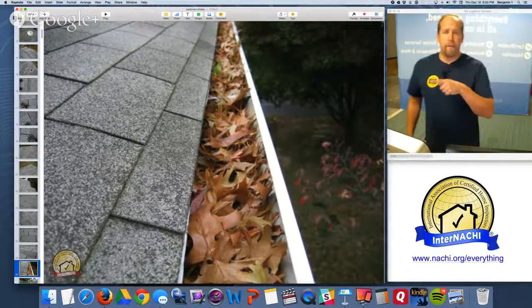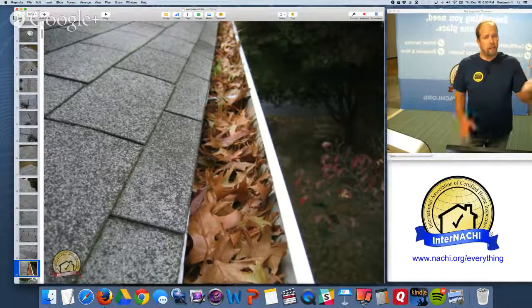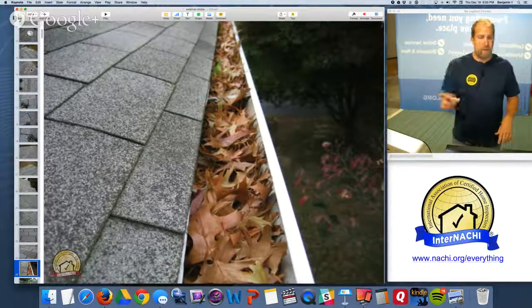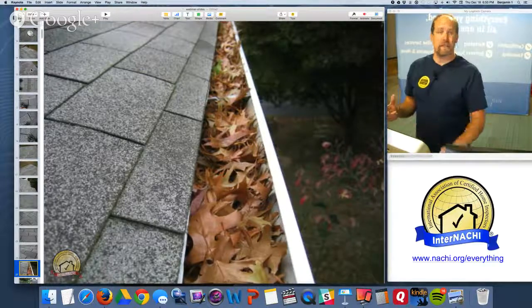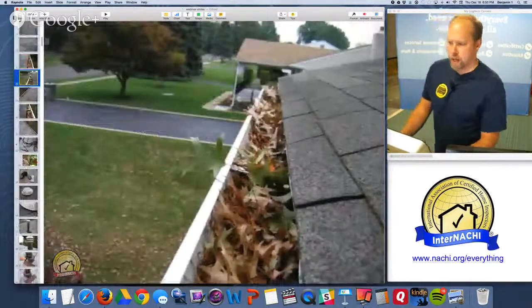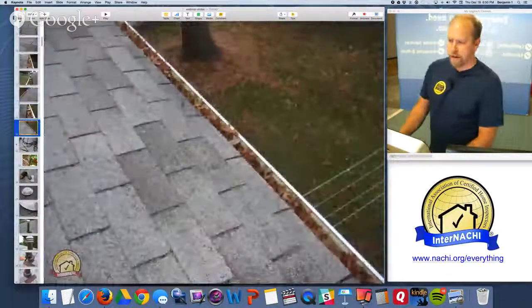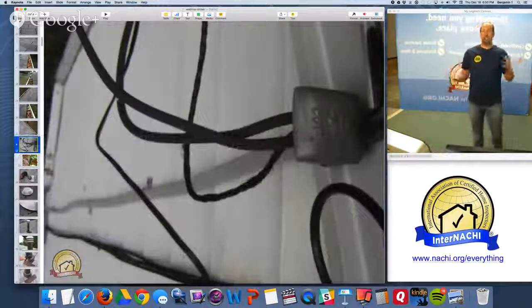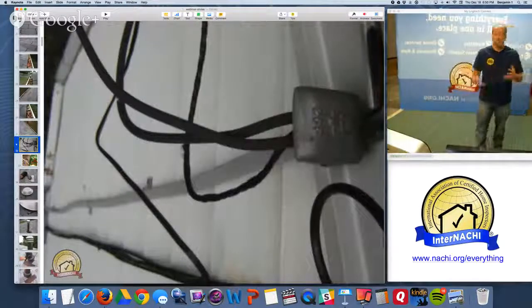When you have 2 layers on the roof, typically when they're installed, feathered in, the first row of asphalt shingles will have a 3-inch exposure instead of a 5-inch exposure. So that's another clue that you have 2 layers of asphalt shingles. Downspouts, again, we'll go a little faster. When I'm on a roof, might as well inspect other systems and components of other systems while I'm there.